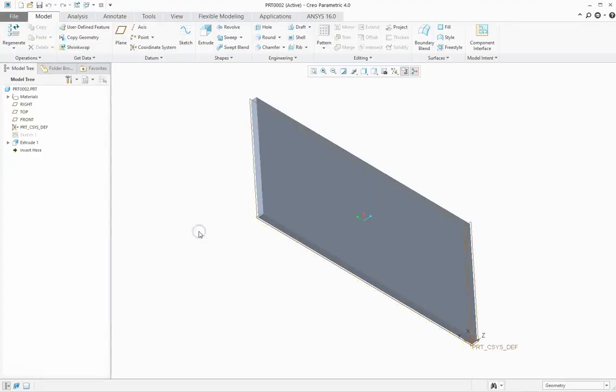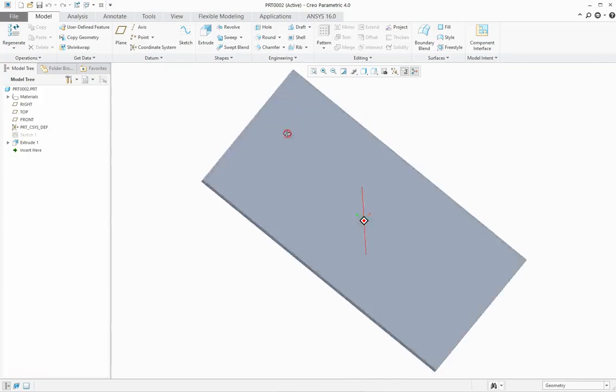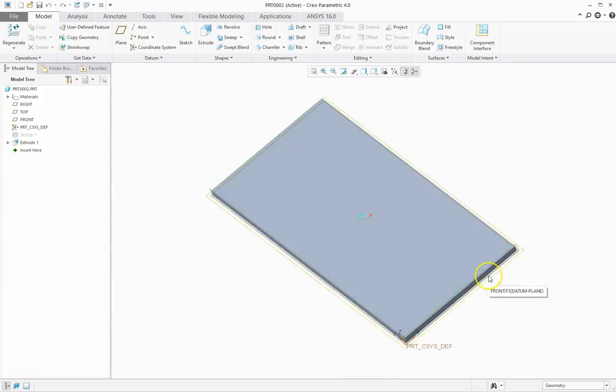All right. So this is a plate, and the dimensions are 10 wide by 20 long, and it's half-inch thick. So we'll apply a tension load of say 500 pounds this way, and then constrain it at this end. In any finite element analysis simulation, well, even before that, let's do something.